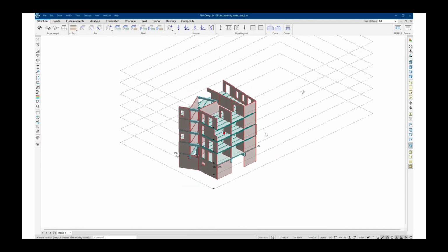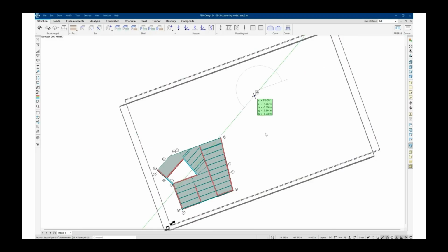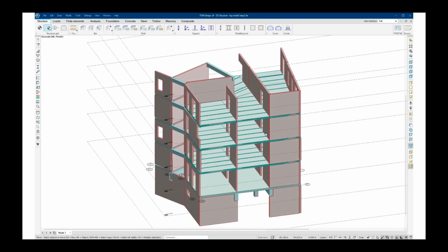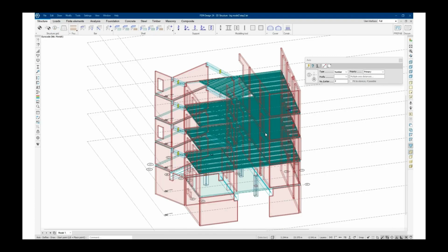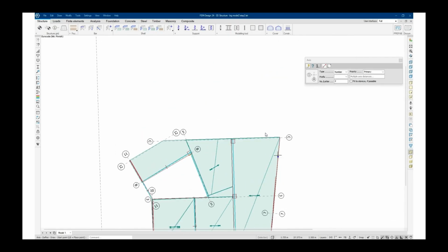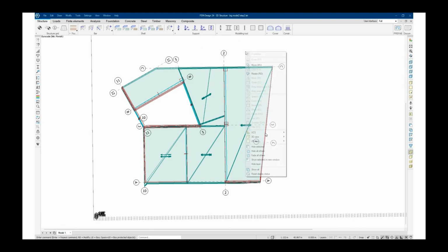It's pretty easy to fill as a table, or you can also set them by selecting plates, and always move the storey system so that your IFC building is inside of the storey system. Then we set axes. And now you think, okay, this is a waste of time to draw some extra axes, but usually making axes even for medium-sized buildings shouldn't take more than 4 or 5 minutes. And if you can save, let's say, 8 hours of modeling, it's totally worth it to define a few axes.